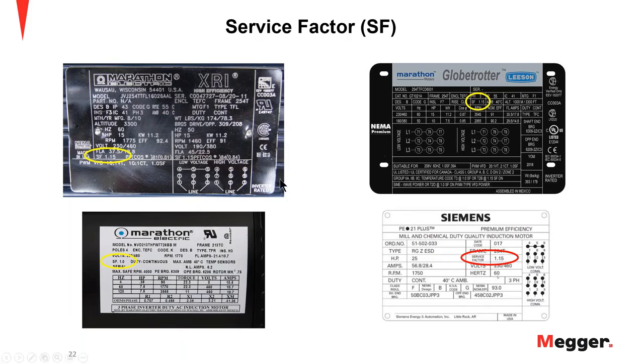Okay, next one is service factor. So the service factor is another value that we need in the calculations for motor protection, also with the thermal limits. The service factor tells us how much over 100% we can run the motor and it still functions at the specified power factor. So the service factors are labeled. All of them are labeled on the nameplate information as well. Each one needs to be looked at.